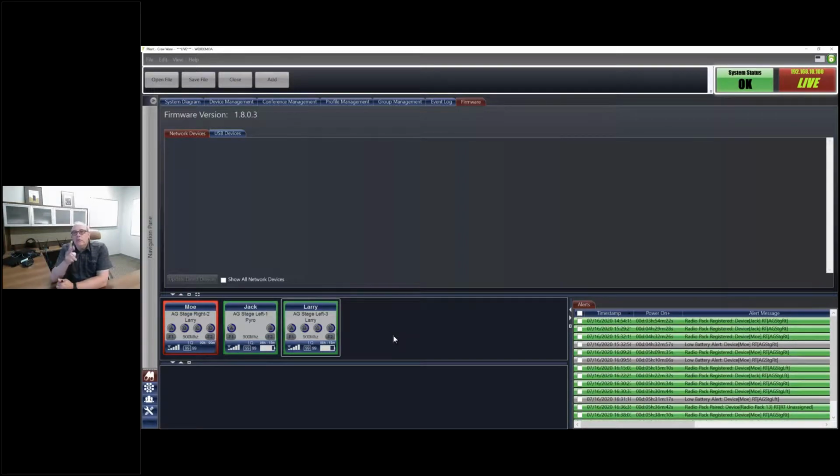Now, since he was using 2 control units, or if you use more than one, the configuration file resides on the master control unit. So it only resides on one control unit. The other secondary, tertiary, however many control units you have, those basically need to delete any configuration files that may have been on them, and basically it gets all of its information from that master control unit. So I just wanted to point that out. That's an important thing to remember.